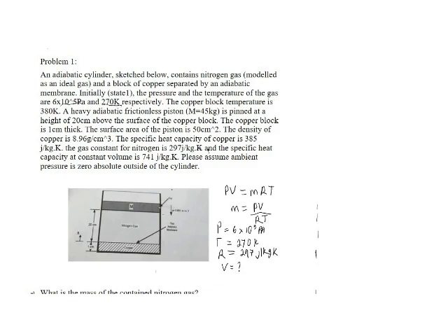The volume of the cylinder is going to be equal to the volume of our gas, the portion that we are going to calculate. From here to here is occupied by our gas, and it has a height of 20, and we're given that the area of our piston is 50 centimeter squared. So we can say that volume is equal to the area multiplied by the height, but area is given as that of the piston, which is the same as the container, which was given to us as 50 centimeter squared.